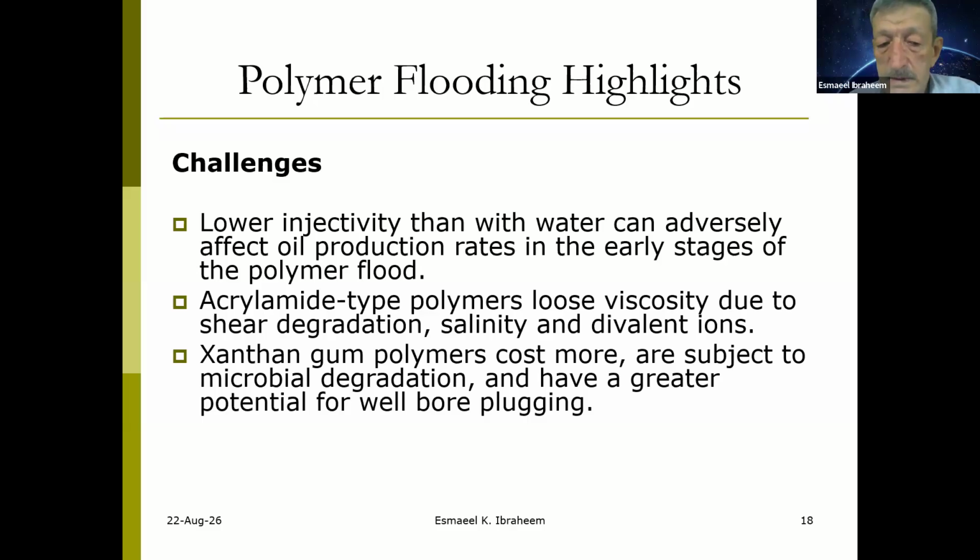As we know, polymers are generally the most expensive material, and have a greater potential for well-bore plugging. This is another disadvantage of polymers. So you have to be careful about the quantity or percentage of polymer in order not to arrive at such a problem, plugging the formation.